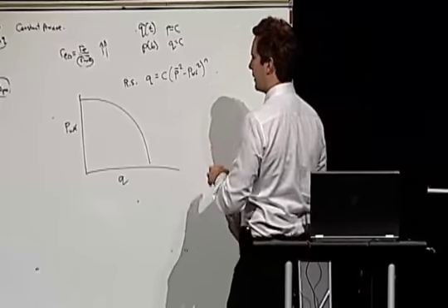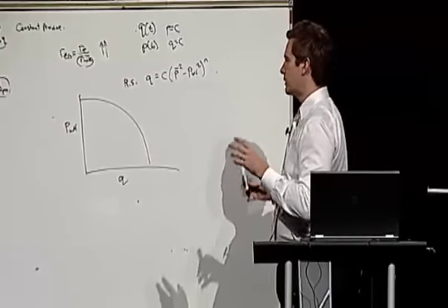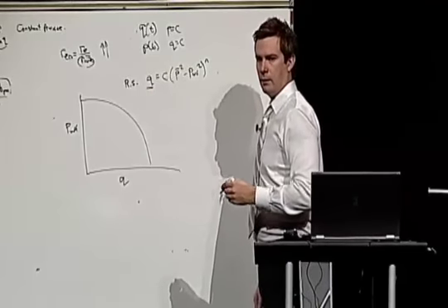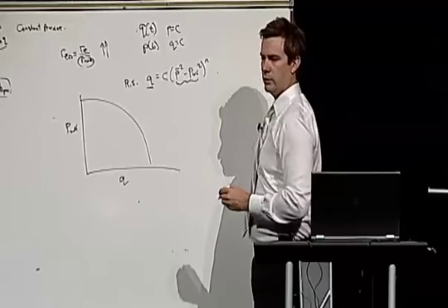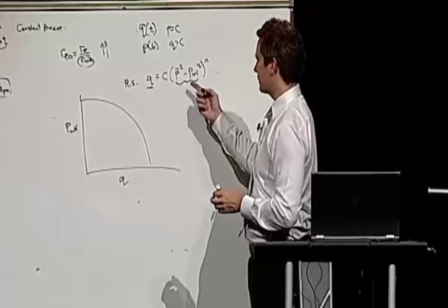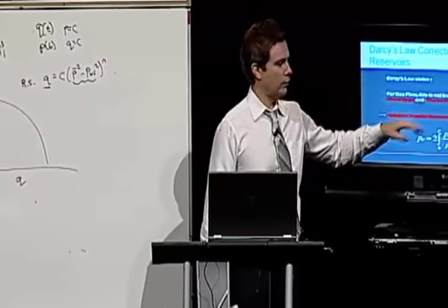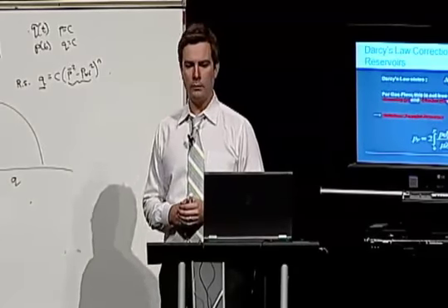What this illustrates is the observation, because this is an empirical equation, that the production rate that you see in a gas reservoir is related not to the difference in pressures, but to the difference in squares of the pressures. Okay? And this is partly due to the fact that viscosity and formation volume factor vary so much in that drawdown region in the well.